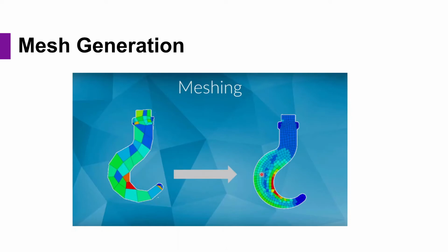which we call the mesh independent model. A mesh independent model is the model that's your goal, which you want to work on and use in industry. Because if you have a mesh independent model, you no longer need to go and make an actual test, because your result would be completely accurate based on what you created, because you already have a really good mesh independency, which from now on, if you change the mesh size and qualities, you will still get the same result.